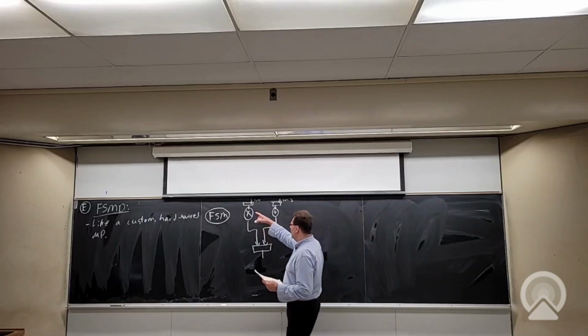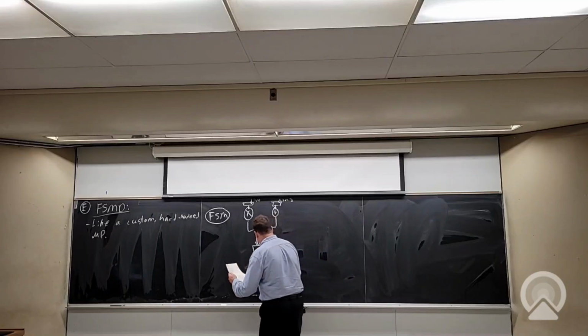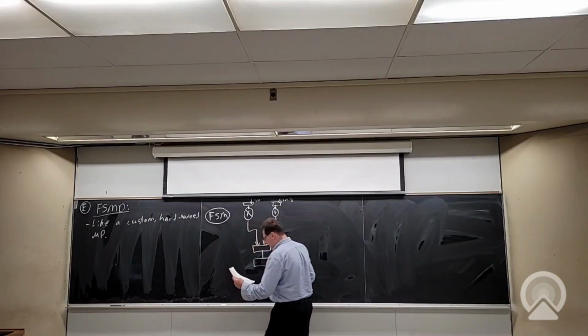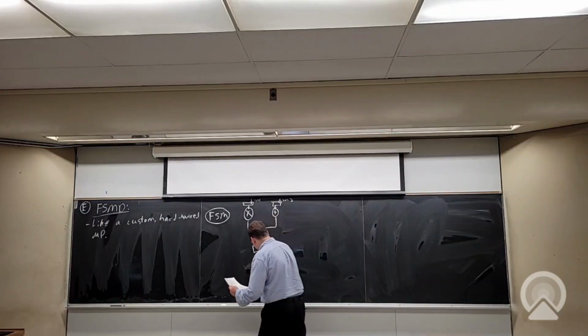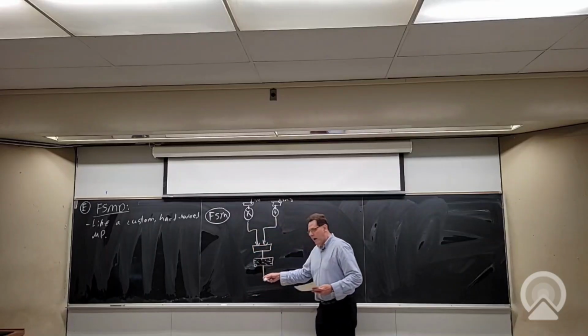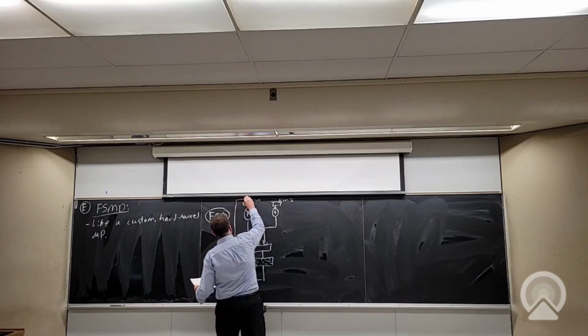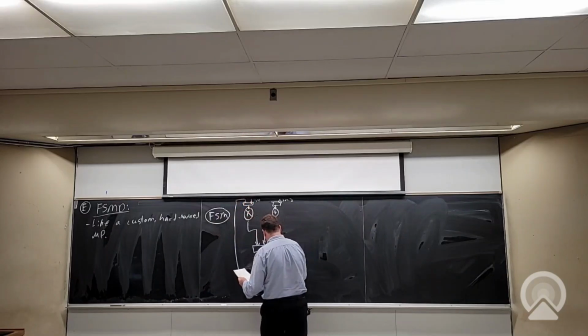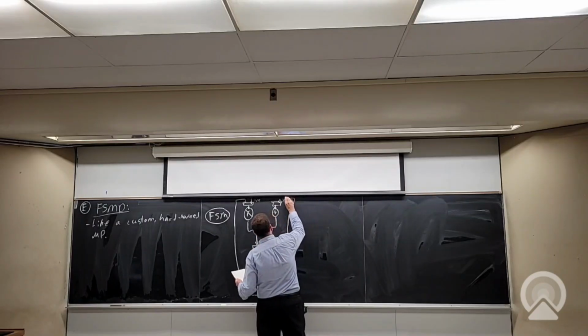So for this to do something useful, I'm going to have to loop back and gradually build up results, because it again is intended for temporal computation. So I'll probably put a bank of registers down here that I can write into. Then I can take data out of this register file as well, and send it back up here for more processing so I can get bigger computations done. And maybe I can send it up here too.